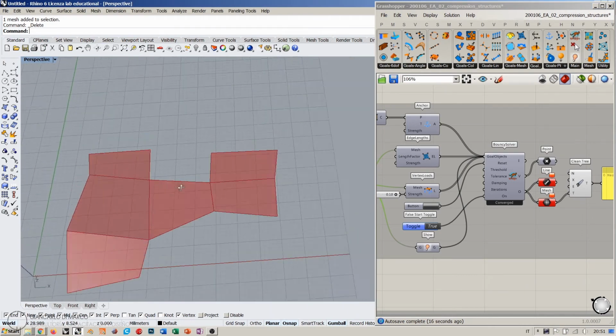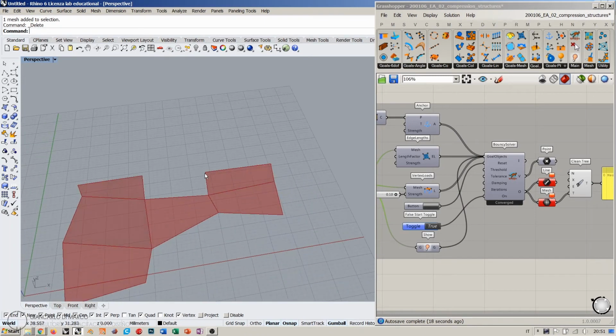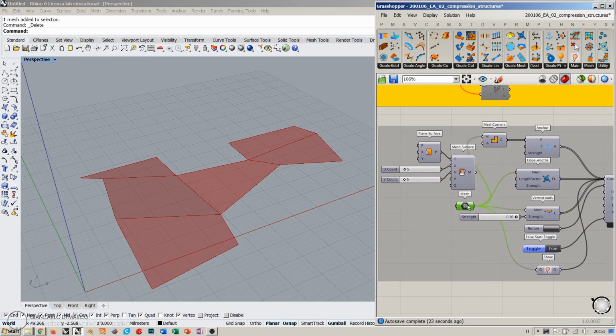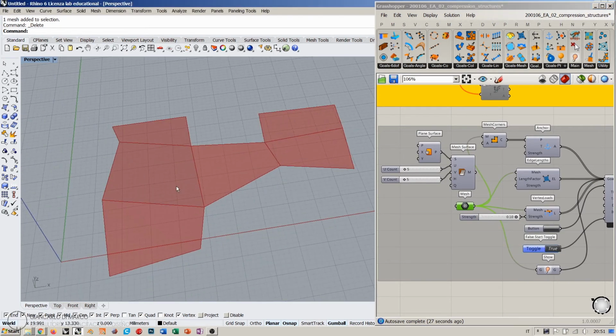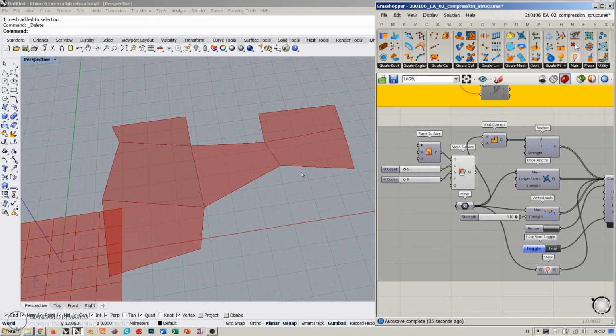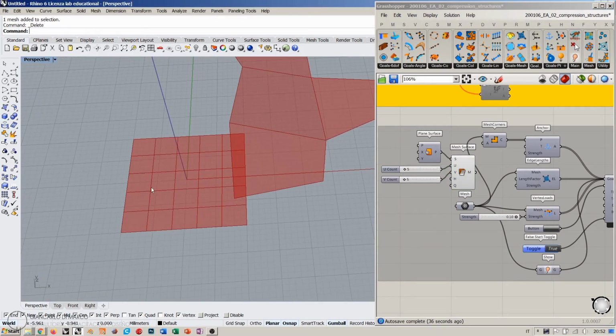Okay, why do we get this strange deformation? Why do we see this object is not bending? Because this mesh is made up of 6 faces, while our initial plane surface was divided into a more dense network of polygons made up of 5 by 5 polygons. They were all free to move. They were only anchored at the 4 corners.